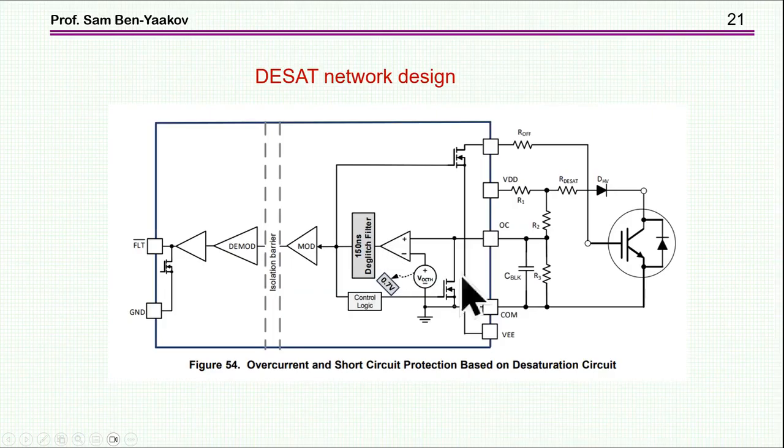So we understand now how it works. Basically, at the beginning, the voltage of the capacitor is 0, you charge it, you come to a point that you are ready for detection, and then depending on the voltage across the transistor, you develop a voltage here, affecting the voltage here, and then the circuit will be activated if the voltage of the collector is above a given potential.